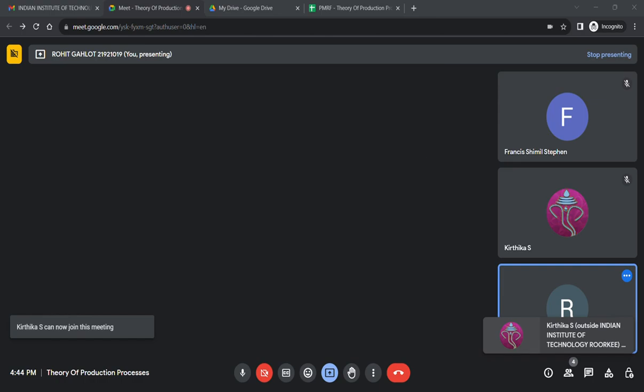So K times V by A. Again the volume you will write as 80 times 120 times 20, now divided by 2 times (80 into 120 plus 120 into 20 plus 20 into 80) to the square. The exponent is 2.